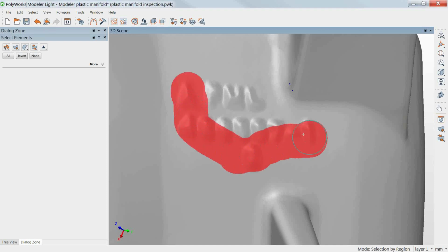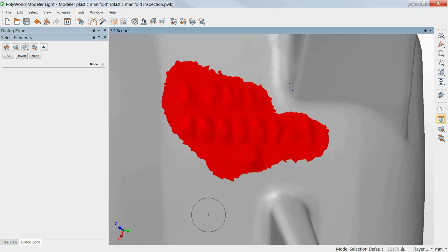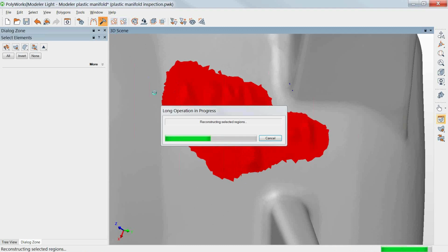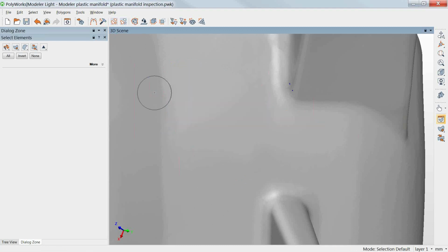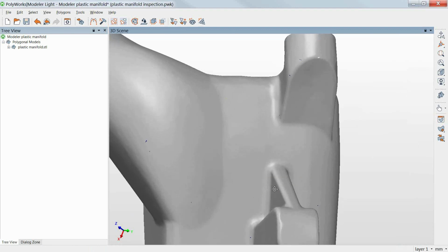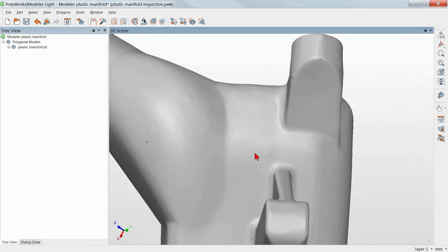is pre-select an area, say this date stamp that's in this casting here. As this goes through, I would like to get rid of that. So I could either delete it and fill the holes in. However, this command will do all of that for me by simply clicking on that. All I need to do is highlight that area, and you can see it's gone and everything's nice and smooth.